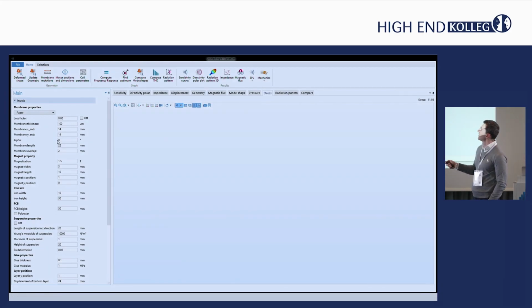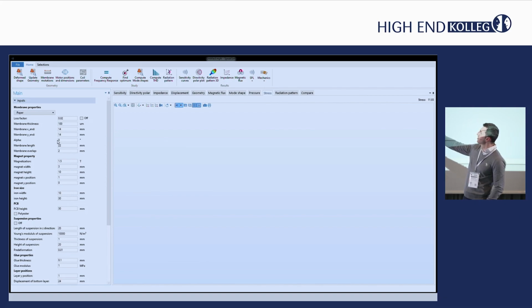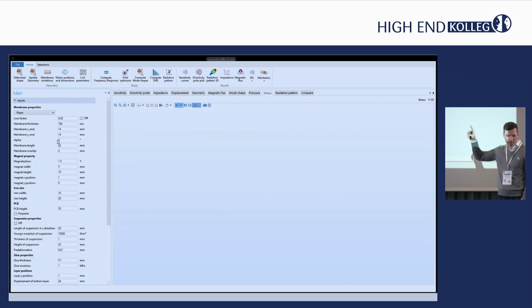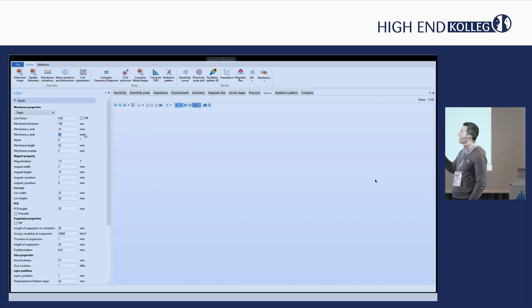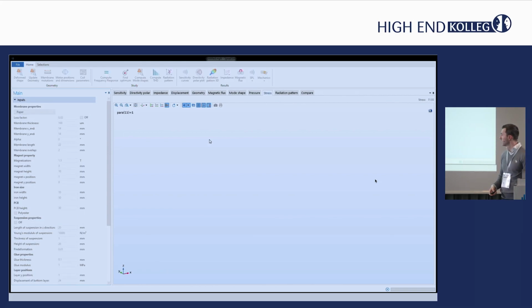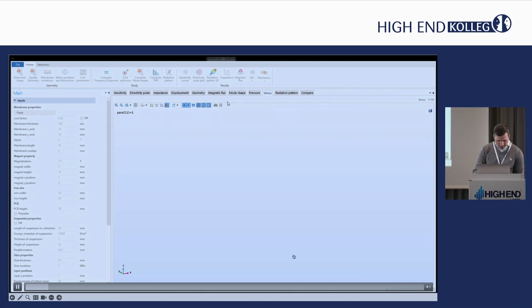So first we need to create some initial geometry, then we need to calculate the deformed shape. That's the first case, and since we don't have the deformed shape and we don't have geometry there, the icons will automatically change the deformed shape and the update geometry to an icon with an exclamation mark. And then as soon as we have the shape, the deformed shape will change, and then we can update the geometry to calculate that one. So that's the first session here.